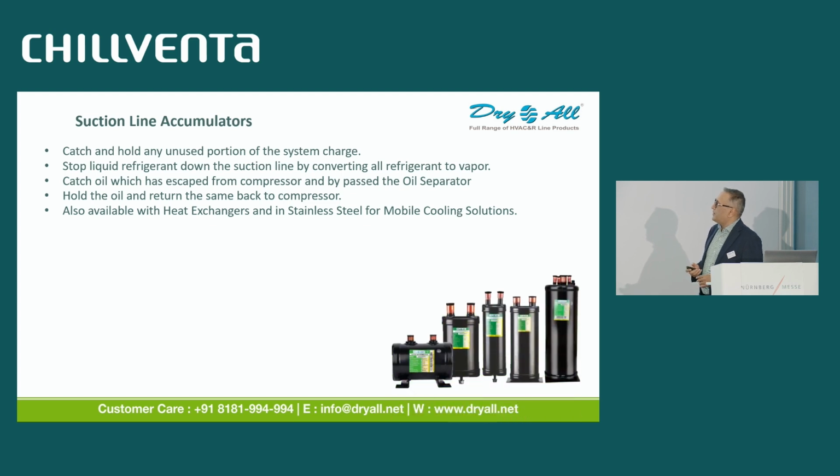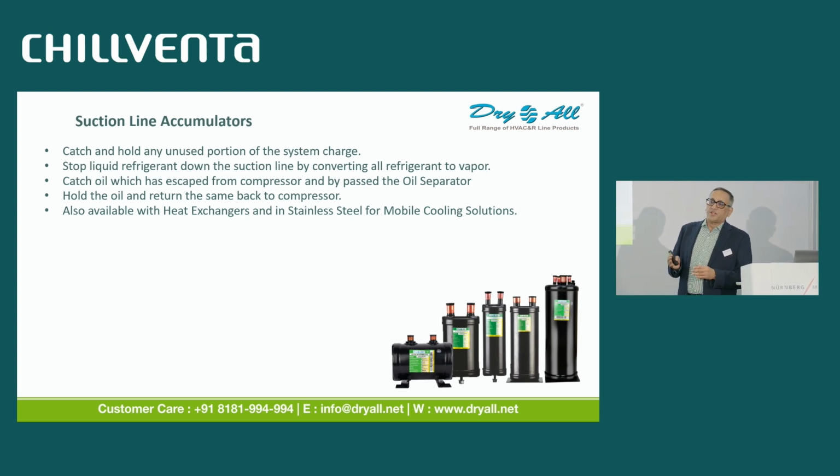Then the suction line accumulator. Sometimes liquid refrigerant will enter the compressor and damage your compressor. But a suction line accumulator just before the compressor converts all the refrigerant into vapor and makes sure that no liquid enters the compressor. It's a very essential component required before the compressor. There's also an oil management system in this. In case some oil has escaped the compressor and the oil separator, it makes sure that the oil is returned back to the compressor, which is very important for the proper functioning of the compressor.